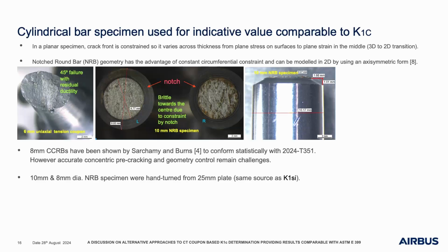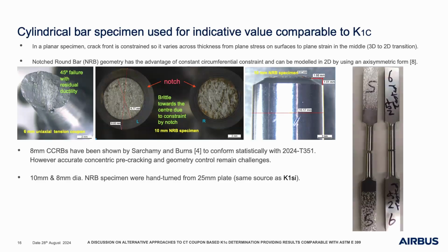It will settle on any negative surface, which is in the circumference. You can see that it hasn't settled in the middle. This is more brittle, and you can see some ductility around the circumference. That's basically what the specimen looked like. I've got them in my bag if someone would like to take a look at a couple of them.